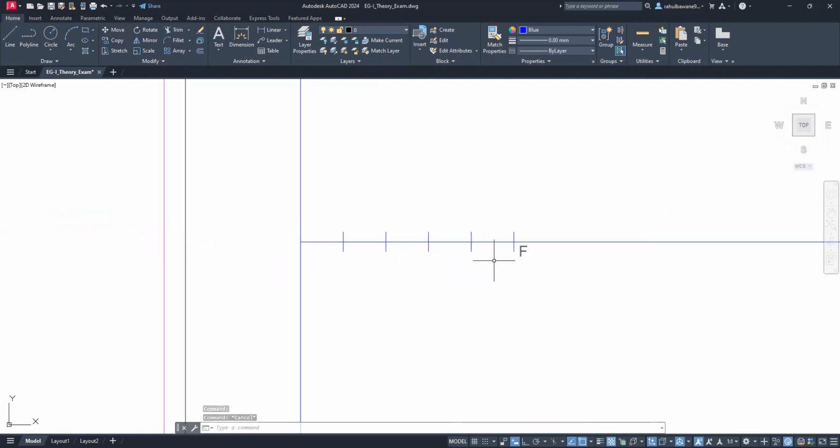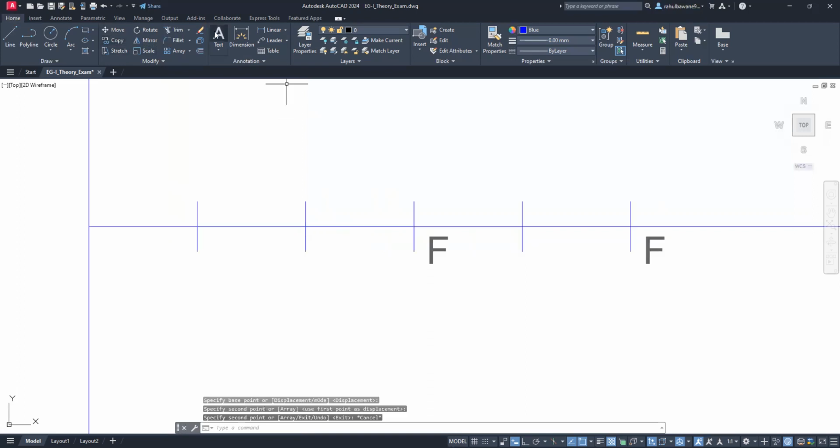Now, as per eccentricity, we have to count whether it is going to satisfy. So first division, second division; first, second, third. So eccentricity 2 by 3 will be satisfied on this segment only. So this is our vertex V. I want to copy this text, because each time we are not going to use a multi-text option.